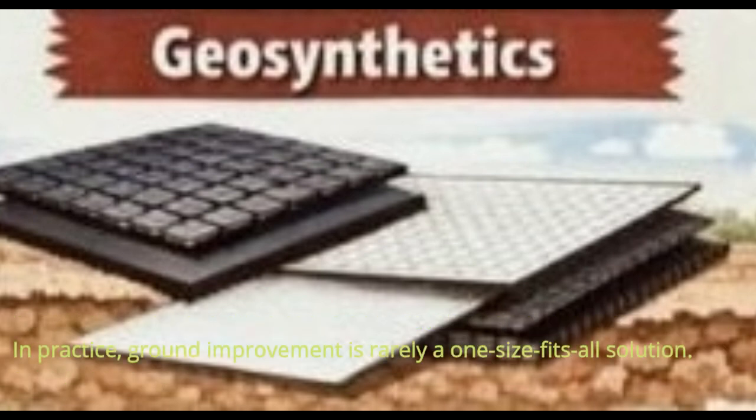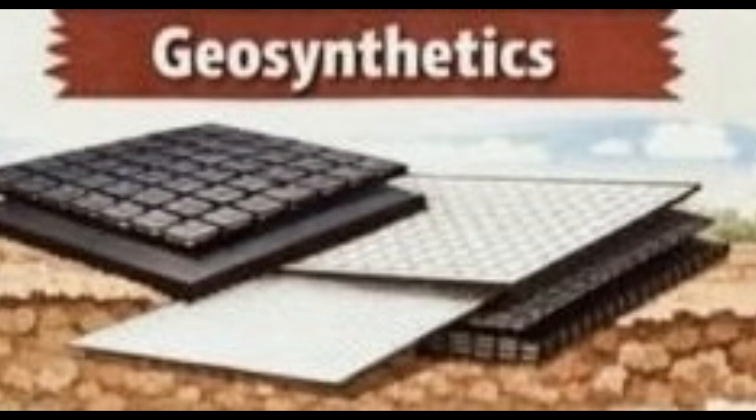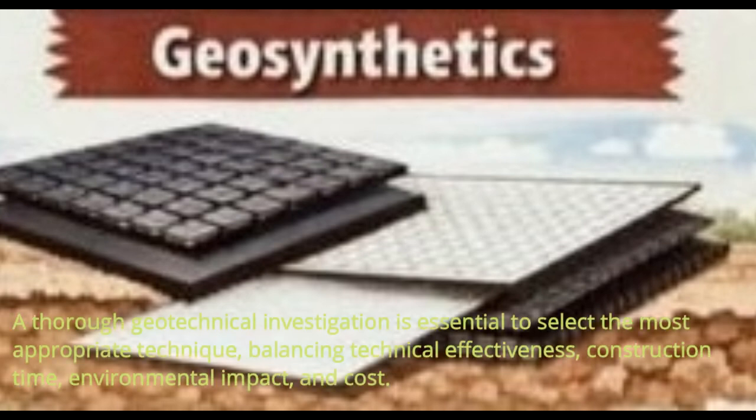In practice, ground improvement is rarely a one-size-fits-all solution. Engineers often combine methods, such as surcharge with vertical drains or geosynthetics with soil replacement, to achieve optimal performance. A thorough geotechnical investigation is essential to select the most appropriate technique, balancing technical effectiveness, construction time, environmental impact, and cost.